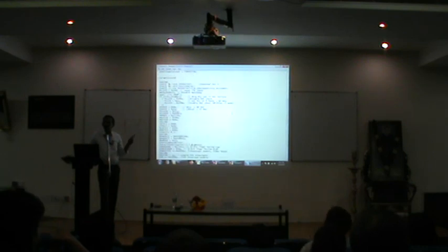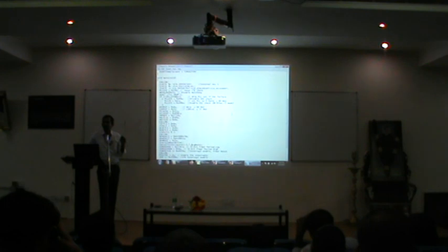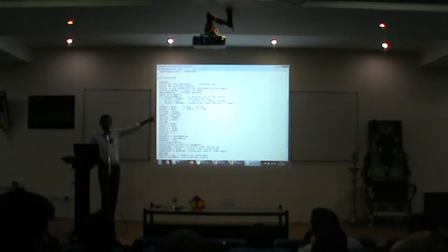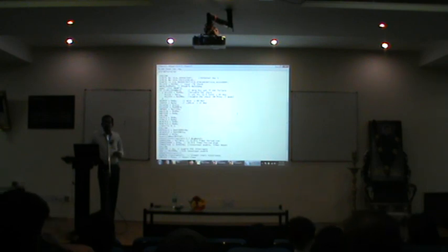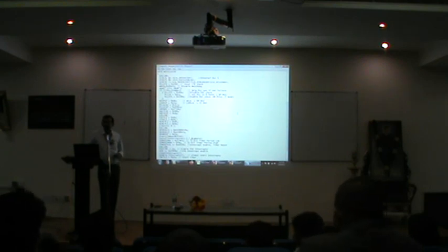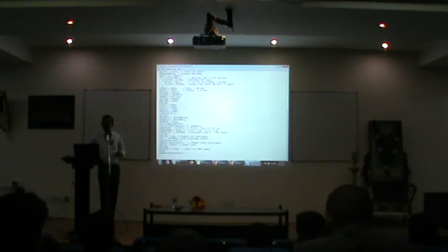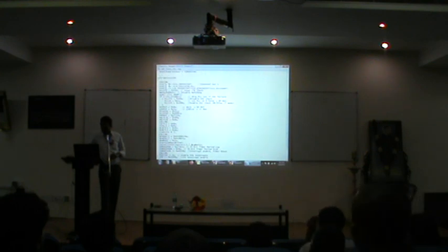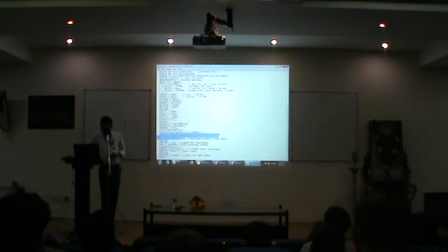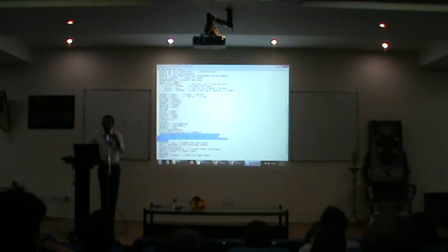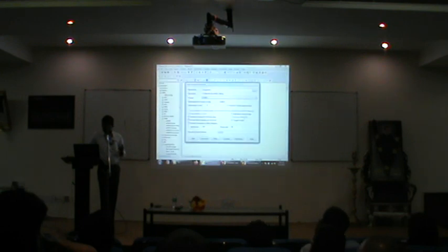Now the logic which we have created is only PWM logic, PWM generation logic. But in addition to that, see what and all is there. There are some chip features, general chip features which you have to configure. Starting from PIE all the way to watchdog timers. All those things are by default configured there. And including your, where is it? Yeah, see this? Time and period, compare register, action qualifier, everything is populated there. So naturally it is going to cut down your development time. That is the point which I was trying to make.